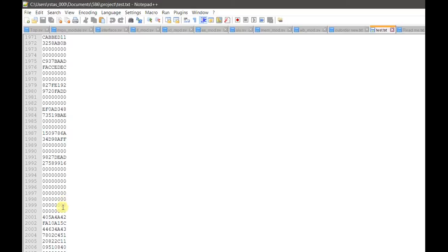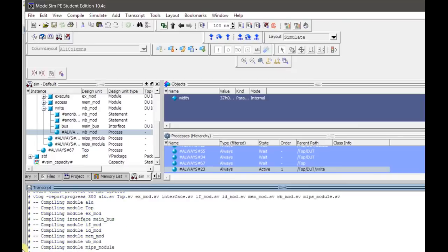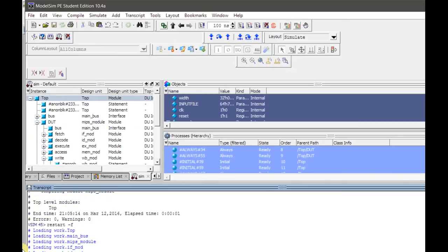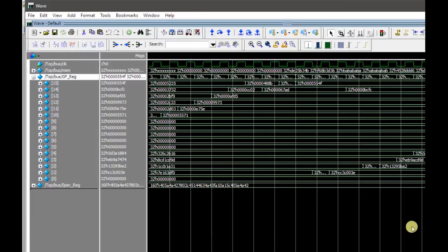We then have the spaces to do the memory write back of the encrypted data, which we can quickly show in ModelSim. So we have our data key, and then our first data, and then the solution from homework 3. So our IDEA algorithm is correct and it works. We then can show our special register, which we can do any part select on because we have the extra 32 bits on the top end.